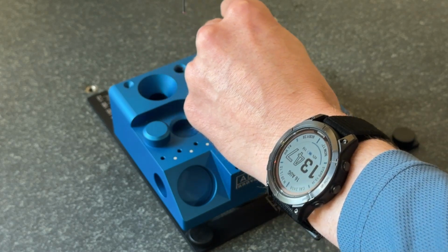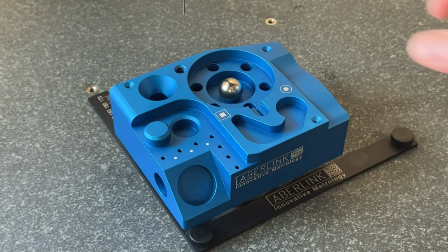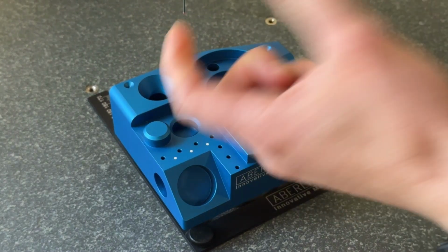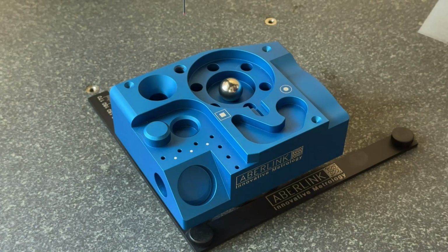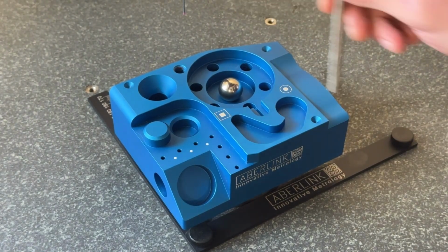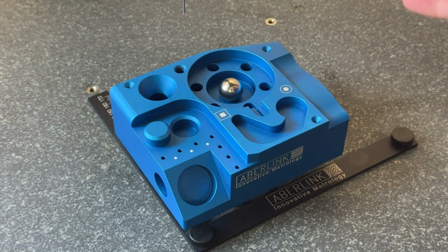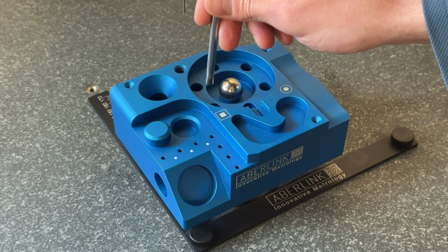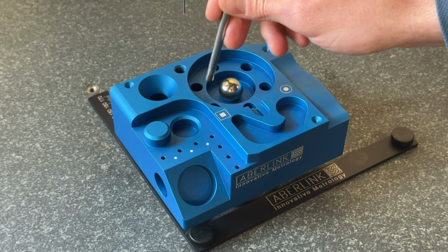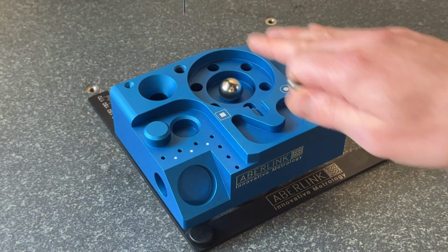this pocket. So imagine this is like a face groove and I want to measure this plane. I'm going to be going very close to the edge of this circle and the sphere when I take the two circular planes, and if that was to drift at all, say it's been done in a different operation, etc., the likelihood is it will crash. So I want a way to be able to zero out so that the position always stays true to itself.